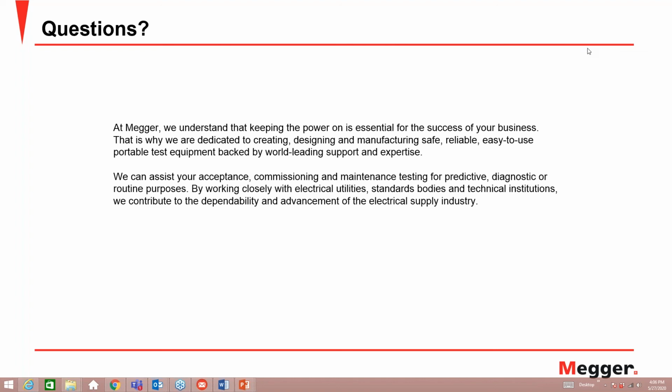All right. Sanket, our next question's for you. When testing NiCad battery straps, do we need to take the battery out of the string? So Andy kind of went over this while talking about impedance testing on NiCads. It depends on the equipment that you're using to run the test. If you use the Byte 2, for example, it injects current through the whole string.